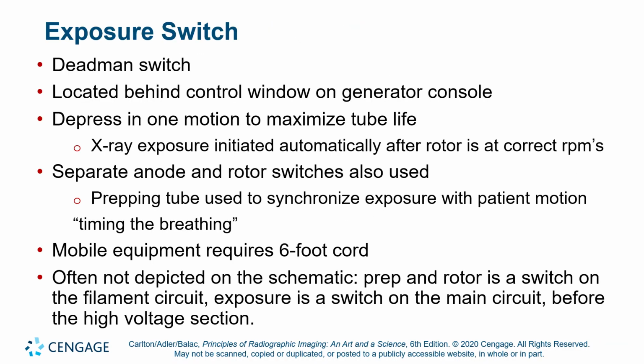Our exposure switch has to be a dead man switch. That is, if we're taking an exposure, and this is most important for fluoroscopy, but if we're taking an exposure and the X-ray operator, whether it be radiologist or technologist, has a heart attack or passes out or some such thing, we want the machine to stop exposing.